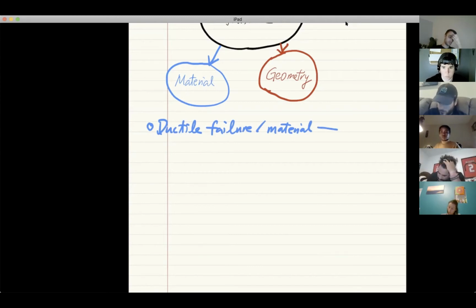Well, we define this as a ductile material because in the stress-strain domain, the x-axis being strain is usually denoted by epsilon. And the y-axis is usually denoted by stress. Stress is denoted by the symbol sigma. You must know that, right? Even after summer, you still should remember this.